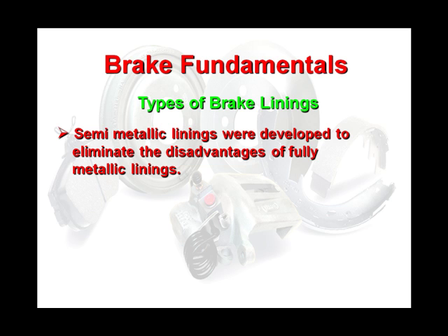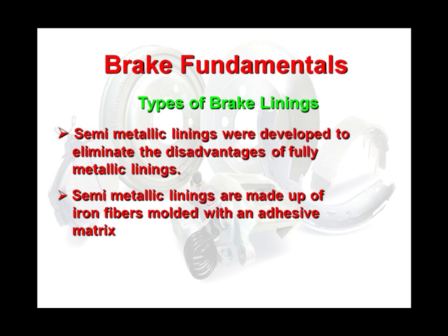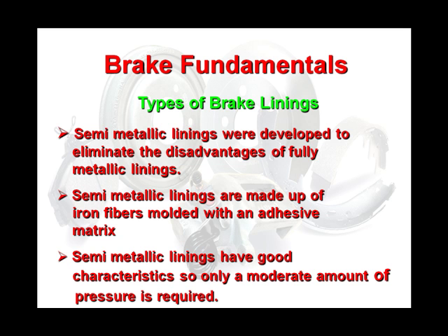Semi-metallic linings were developed to eliminate the disadvantage of fully metallic linings. Semi-metallic linings are made out of iron fibers molded with an adhesive matrix. Semi-metallic materials offer excellent fade resistance that meets the needs of today's vehicles. It has good frictional characteristics, so only a moderate amount of pressure is needed. Semi-metallic pads and shoes do not cause excessive amounts of wear on pads, drums, and rotors.